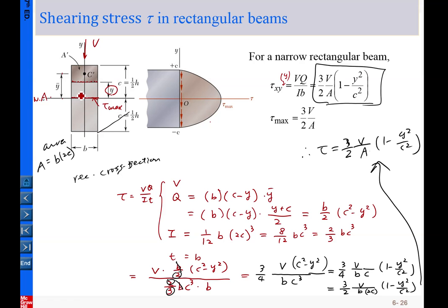Okay, again, the direction of the shear stress is like this. So at any level, the direction of the shear stress is like this. For this case, this is the component. This shear stress is in the x-plane because this plane has its normal in the x direction and points in the y direction. That is why we designate it tau xy.